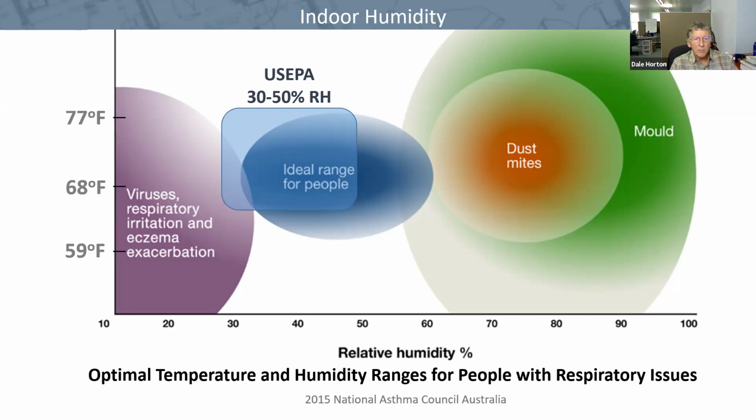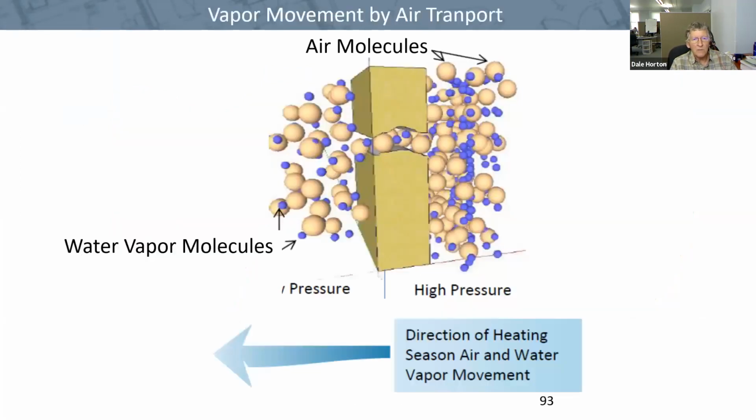The trouble is that builders and designers can't entirely control what relative humidity occurs in a building. You can introduce some design elements such as dehumidistats and ventilation and so forth that can help limit very high relative humidity. And of course, in some environments, you both dehumidify and humidify based on the health needs of the occupants. But 30 to 50% seems to be the sweet spot in terms of relative humidity.